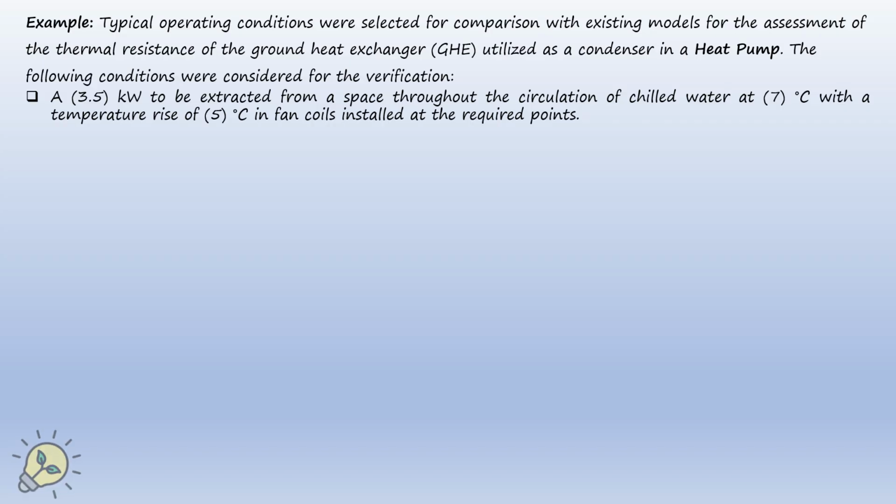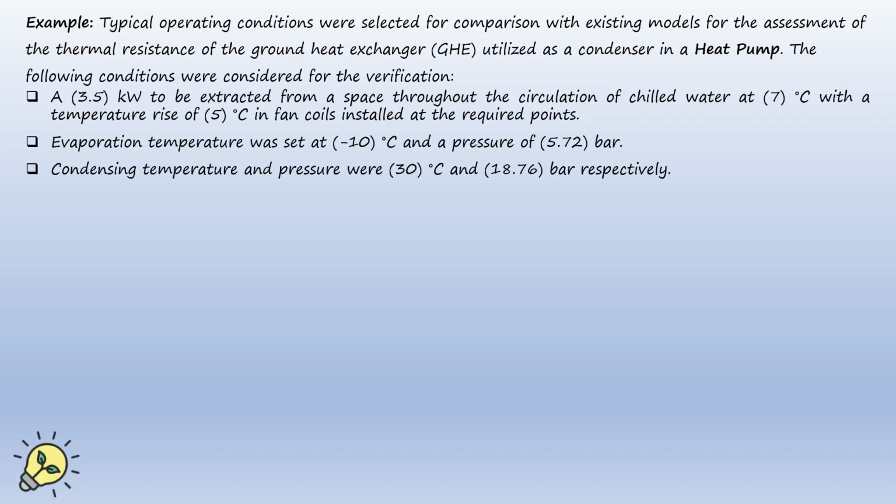The evaporation and condensation temperatures are as shown in this expression: the evaporation temperature is minus 10 degrees Celsius and the pressure 5.72 bar, and then the condensing temperature and pressure were 30 degrees centigrade and 18.76 bar respectively.